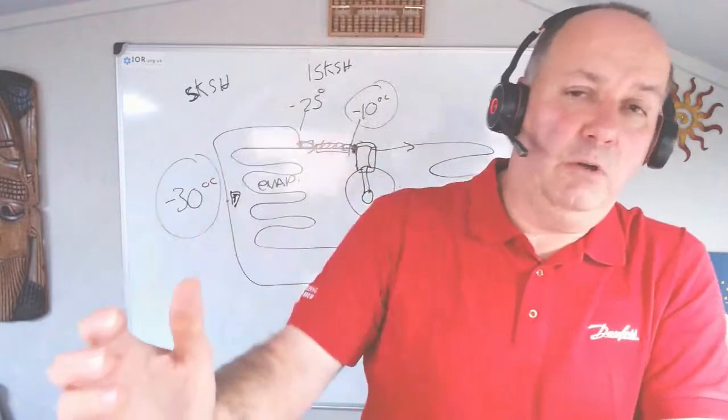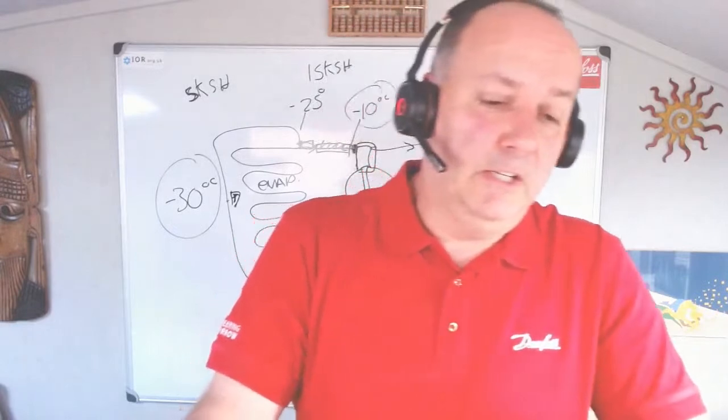What we don't want to do is open up a valve instantly and allow all this hot gas to rush into the cooler, because that thermal shock can cause vibration, it can cause fracture, and in a lot of cases it's led to fracture, and particularly with ammonia systems, even CO2 systems, that can be incredibly dangerous. So if you are using hot gas on an industrial system, please make sure that you've got two-stage opening valves or slow opening valves. But sorry, Stanley, I can't tell you that stage without looking at a document, so apologies for that.